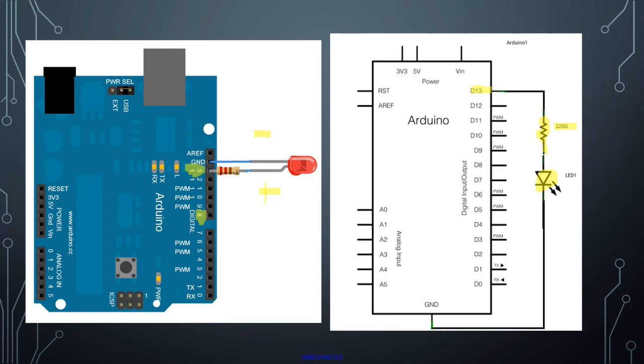And you can see in our schematic, it even helps us note which is the anode and which is the cathode side. So here, the cathode is the negative side, right? And we know we connect the negative side to the ground. And you can see there's this little bar across the bottom of the symbol. So again, that's just another easy way to remember that's where the negative side of your LED should be connected.